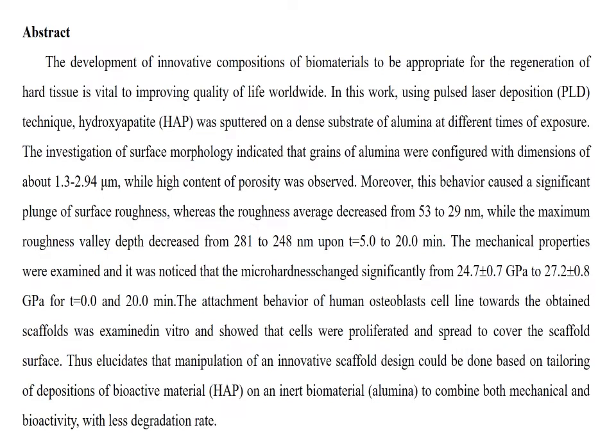First of all, hard tissues consist of two main ingredients: the mineral part, which is hydroxyapatite, and the biological part, which is collagen. The great mechanical properties of bone tissue could be assigned to the ordered structure, which allows scattering the applied load within the bone tissue design. Hydroxyapatite is formed as rod shapes and scattered in well-distributed nanofibers of collagen. This configuration provides good tensile strength based on the nanofibrous contribution and high compressive strength from the hydroxyapatite grains.